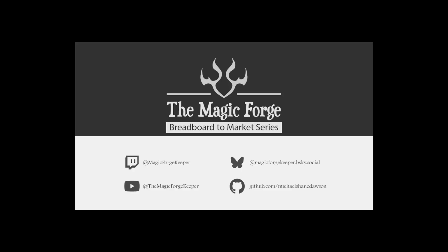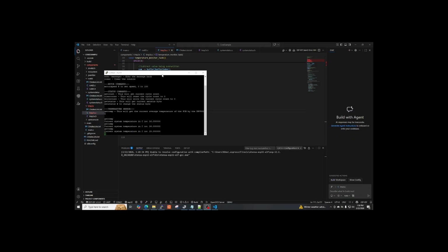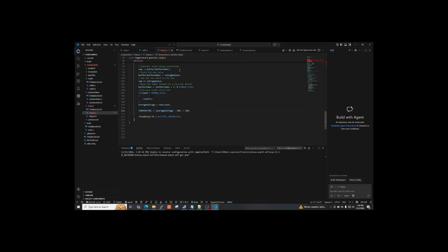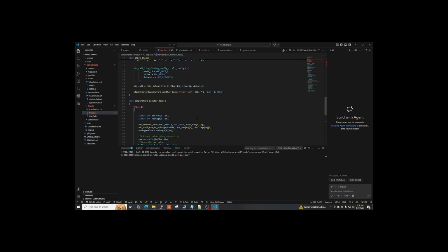So where we left off is we started coding the driver for the temperature sensor. And I'm pretty sure we've got it working. The decimal place was just out by 1. I kind of updated that. So let's go over here. Kind of updated it to divide it by 100 instead of 10. And that put the decimal place more aligned. But there's no decimal point. So let's see if we can figure out how to fix this rolling average.